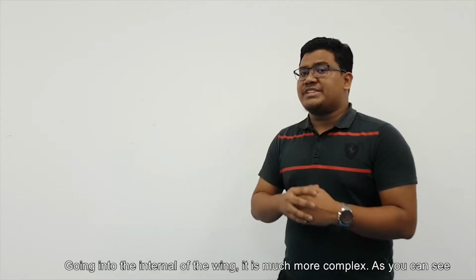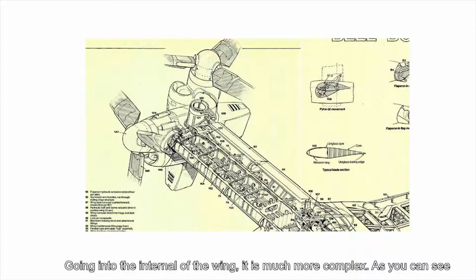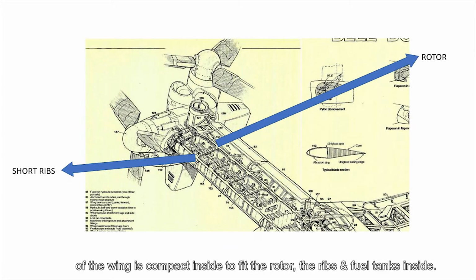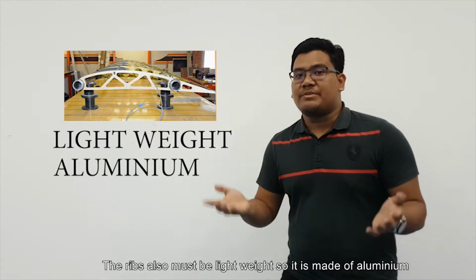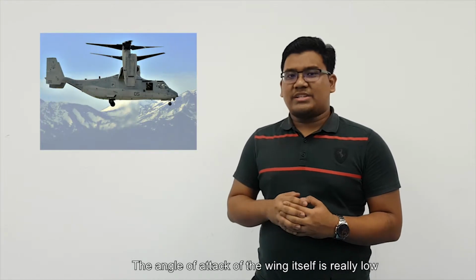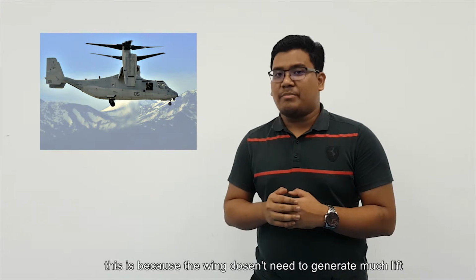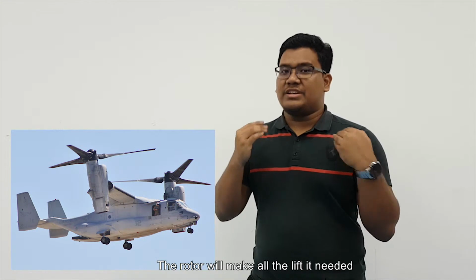lift work. Going into the interior of the Osprey wing, it is quite complex. As you can see here, the ribs are quite short. Well, this is due to the placement of the rotor. So the overall structure of the wing is compact to fit the rotor, the ribs, and the fuel tank inside. The ribs also must be lightweight, so they are made from aluminium. The angle of attack of the wing itself is really low. This is because the wing doesn't need to generate much lift because it has a rotor. The rotor will make all the lift it needs.